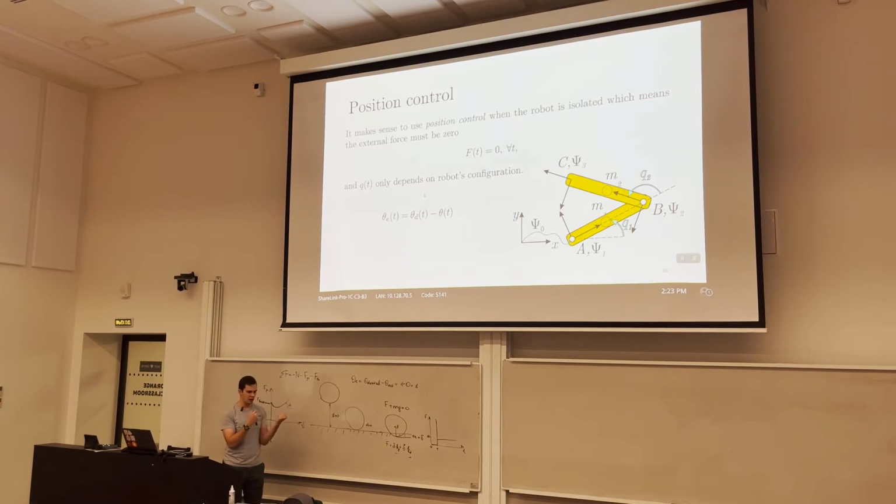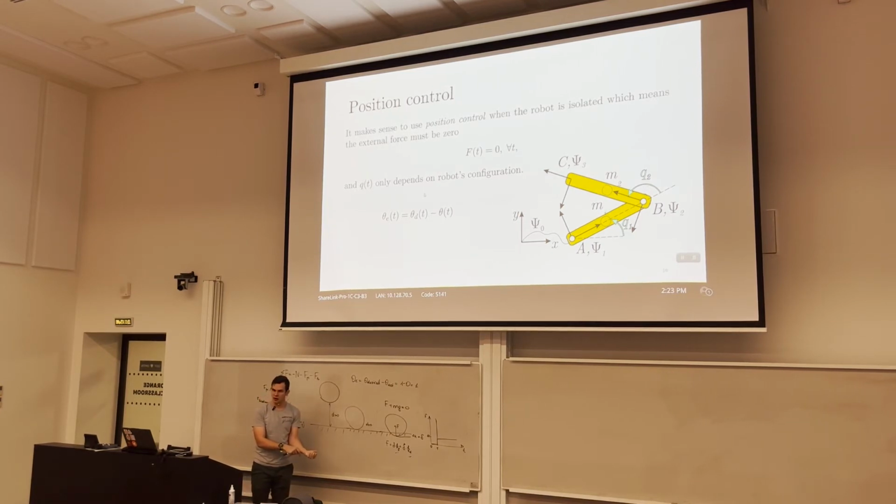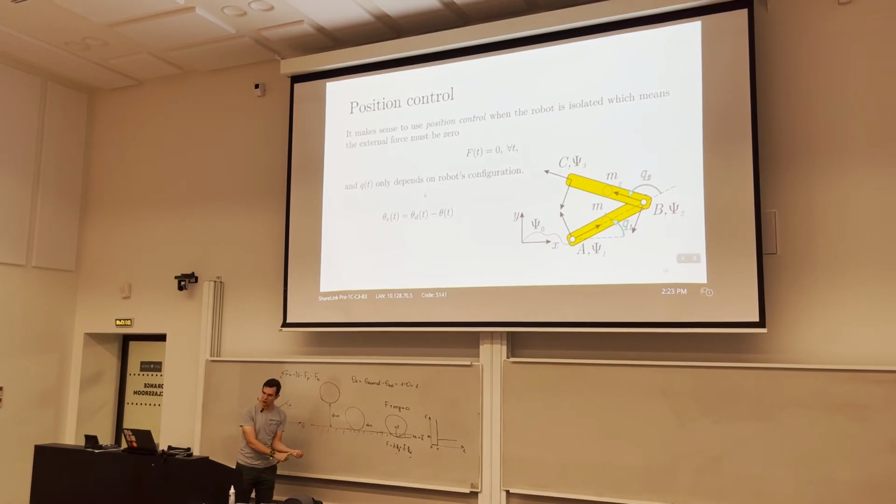And it means that in the very moment of time when we just send the signal, we change the position of equilibrium. It's like we already have a spring that's been stretched, and we can think about our controller as another spring and damper system that's been stretched. So it's like 1 radian now is the position of equilibrium, but we stretched it and it bounced like this.